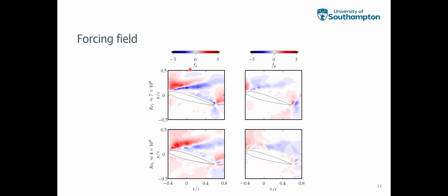And he noticed that the scaling of the forcing was in terms of inertial quantities, which is the free stream velocity and the chord length. If you consider this to be an acceleration term, which is made of meters per second squared, you can use a combination of the free stream velocity and the chord length to normalize this forcing. But since in my case I have already normalized the chord and the free stream velocity, we think that this is already a normalized forcing and does not require further normalizing, if that makes sense.